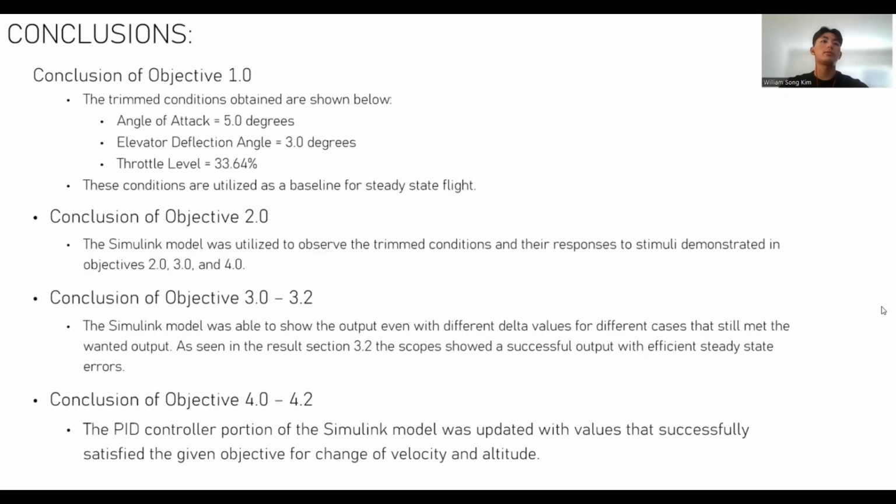Lastly, for conclusions, for objective 1, we were able to find the trim conditions as shown. We had the value of 5 degrees for angle of attack, 3 degrees for elevator deflection angle, and 33.64% for throttle level. We use these conditions as the baseline for a steady flight.